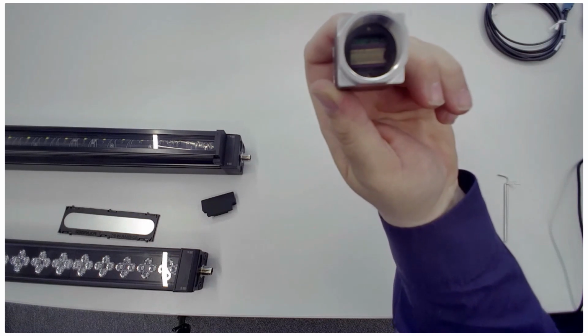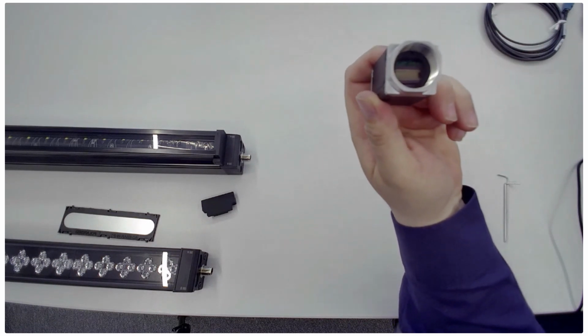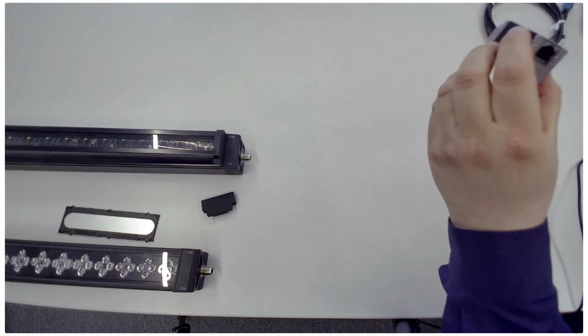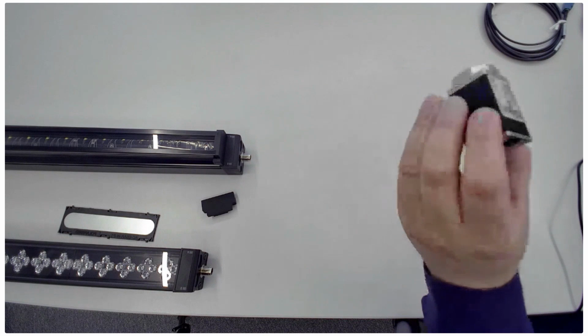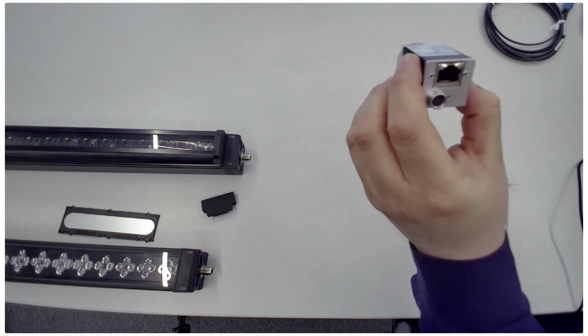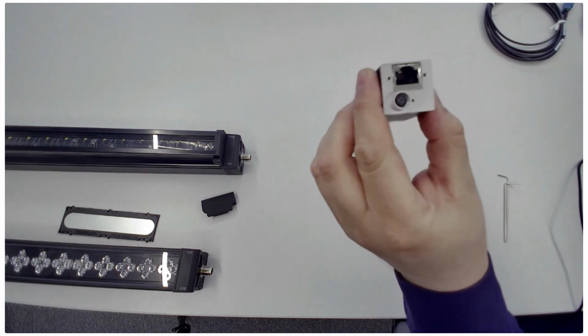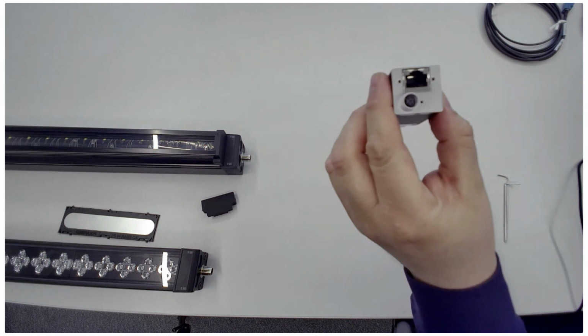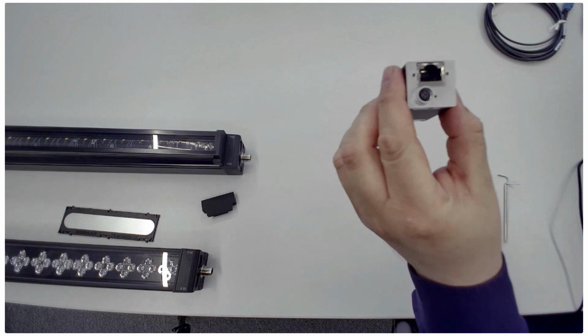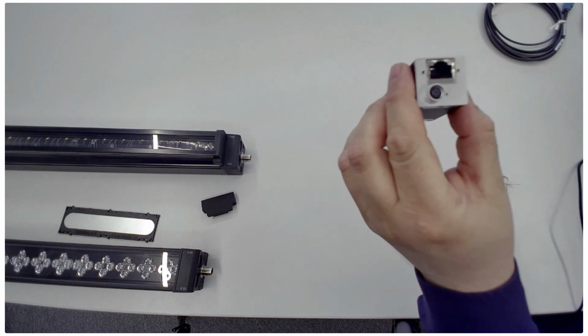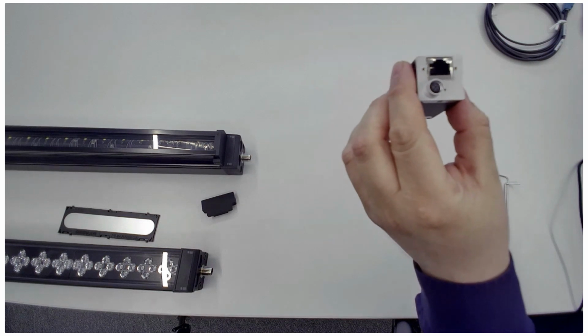So this is what it's all about with line scans. And here we also have the GigE connection, and a circular connector for IOs, inputs and outputs. Here we provide the electrical signals from the encoder, for instance, to synchronize the camera along with the process.